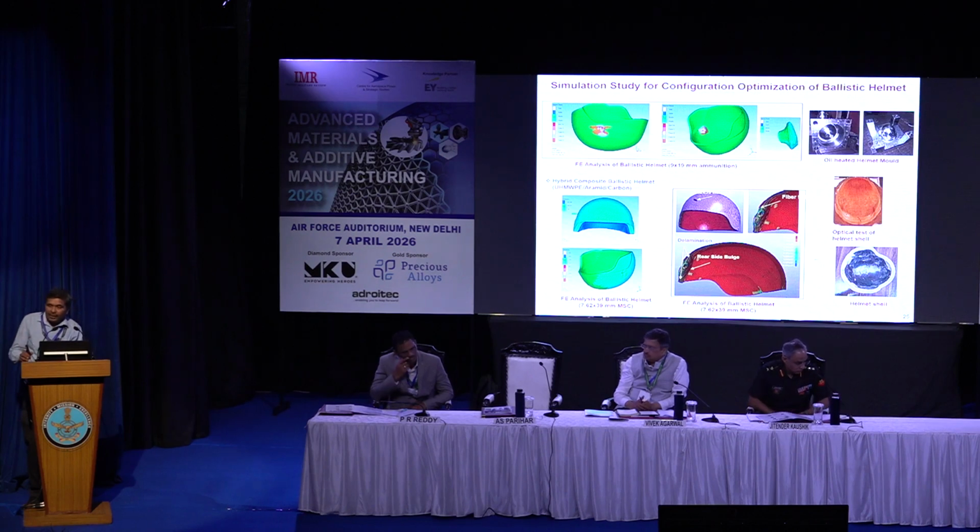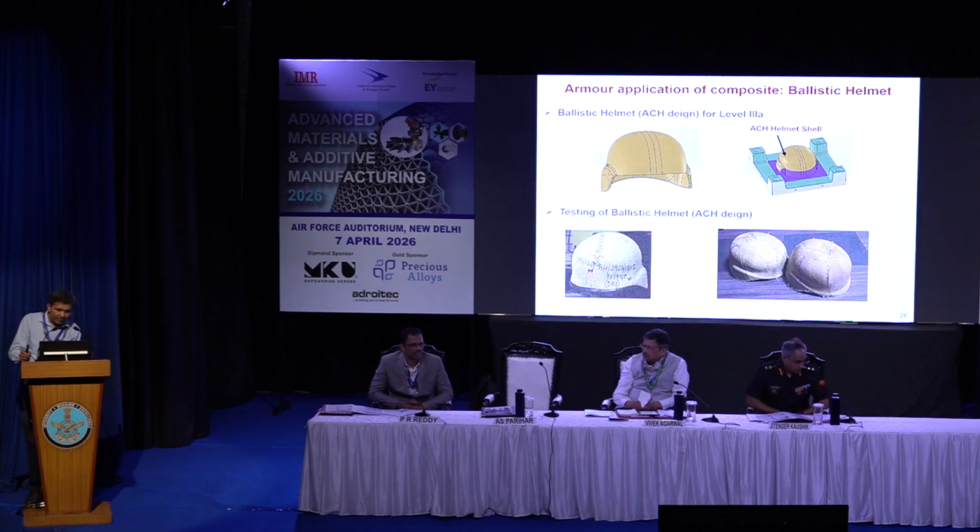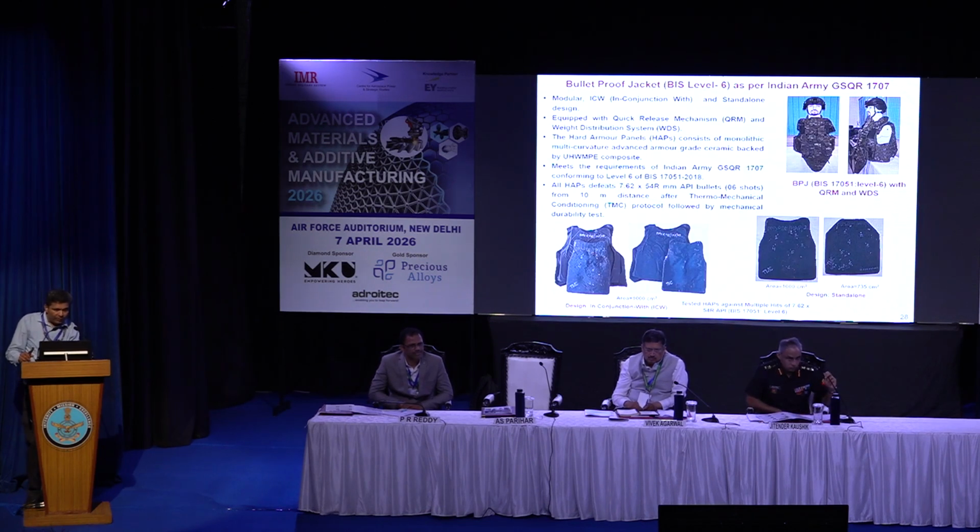So a lot of study has been done by DRDO, but some more study will be required to convert those traumatic brain injury effects into a quantity where we can say that this value of backface deformation will lead to such an amount of traumatic brain injury to the head. So these are all the studies we did, and this is the study for the monolithic ceramic plate. Again, by designing the ingredients of the ceramic, even the monolithic plate is able to stop 6 rounds of the sniper within the close vicinity shot of 51 to 55 millimeter.